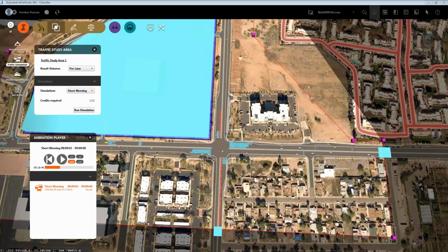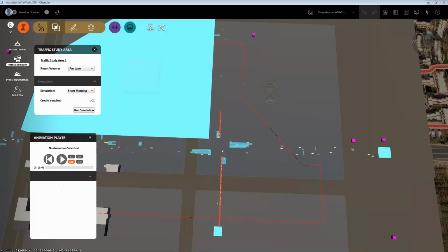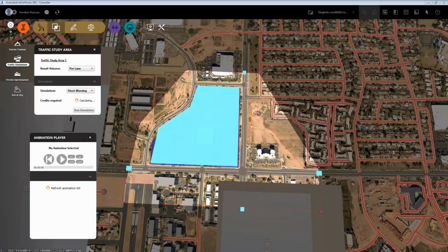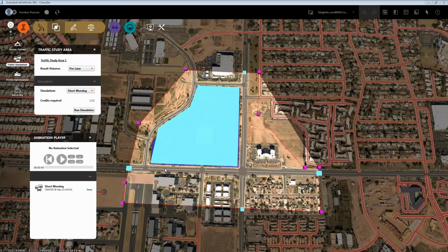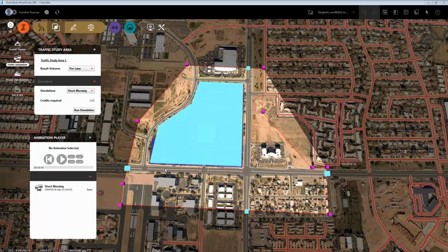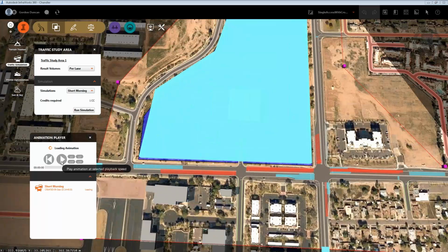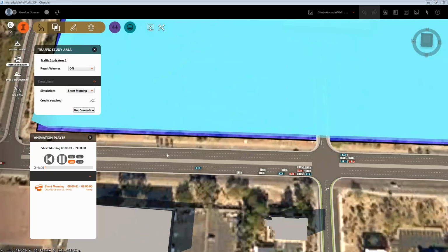One of the things that's in one of the proposals, quite a few people have asked for, is can we model pedestrians in any way? So there's a third proposal that has a pedestrian crossing in there. Right now you won't see any pedestrians in the main InfraWorks window here, but you will see the traffic stopping where the pedestrian crossing is. So if I just switch off the coloured bars for a moment, the pedestrian crossing's about here, going across the middle of this road, and you can see that's why these cars are queuing there.